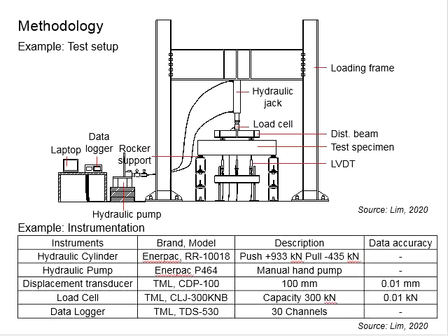Based on the failure mode, specifically, you are observing the critical crack and you assume the failure mode of the member. Is it really the failure mode as what you have perceived? And then based on the crack pattern, probably measurements given by the strain gauge, you will assume the stress developed within the member. On the basis of some prior understanding, maybe you can suspect where the highest stress region is. Is it actually true? Nobody knows.